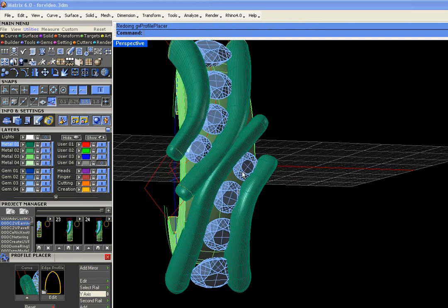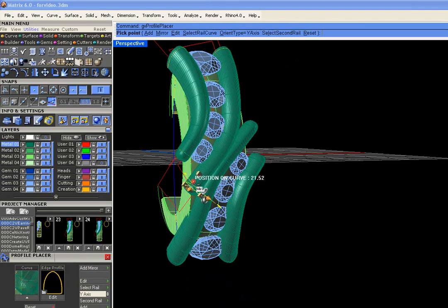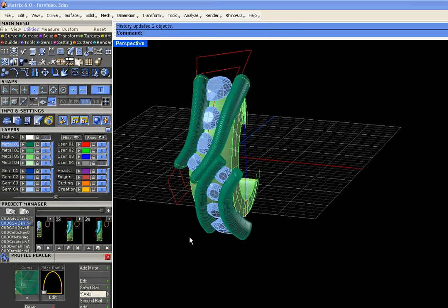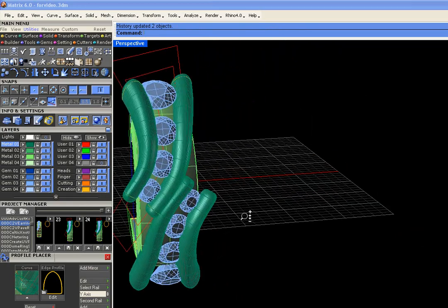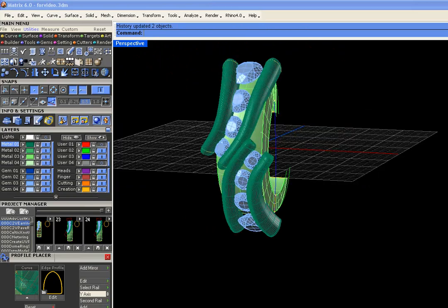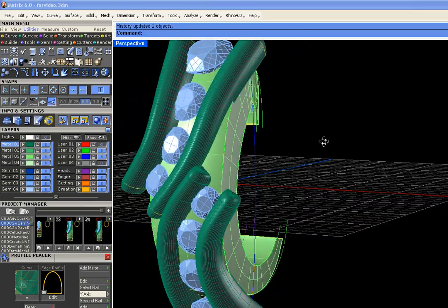This is a really powerful use of these tools. This one's a little too far for our design. Let's say F6 MSR, position on curve, and just sneak it back. Enter. And it shrunk this side as well. Okay, so here's a completely history-enabled model thanks to rhino history and matrix history. I'll just turn off some of the curves here, and we can shade it up and see the results.